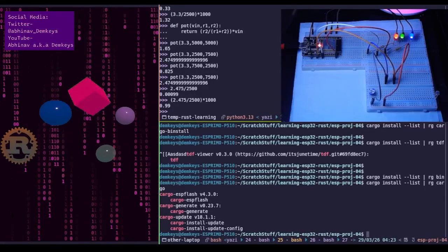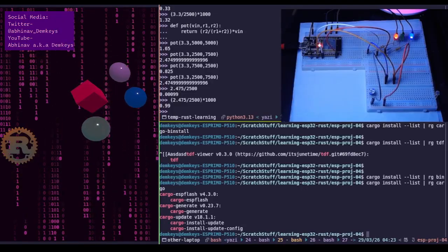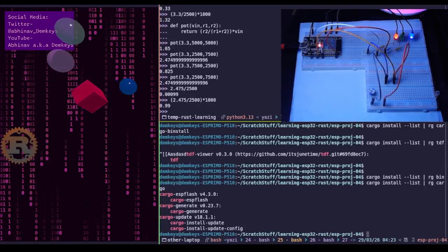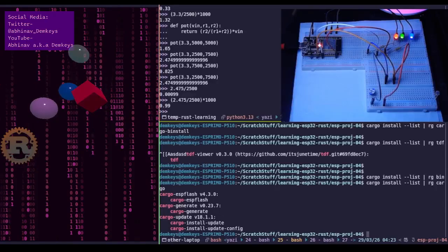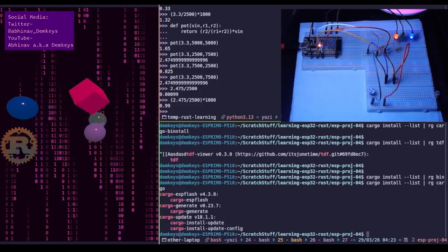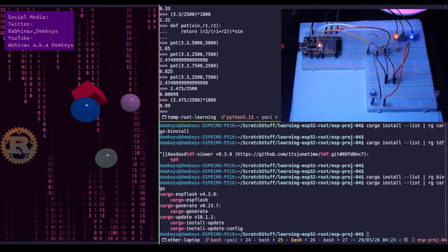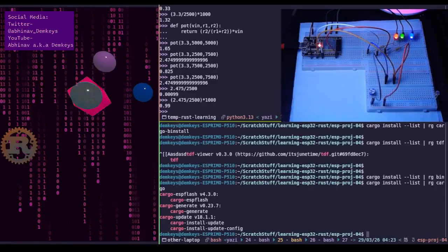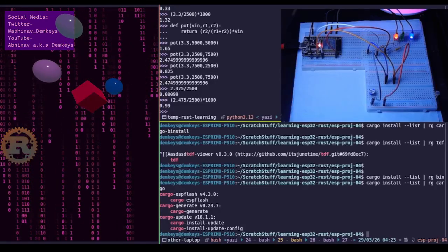Anyways, so they're suggesting using cargo install. I prefer cargo install instead. They're suggesting cargo install for installing ESP Flash. I don't remember if we have to install ESP Flash separately, or does it come with ESP generate? I don't think it does. I think I had to install it separately because the flashing utility is separate from the generation utility. They're not the same thing.